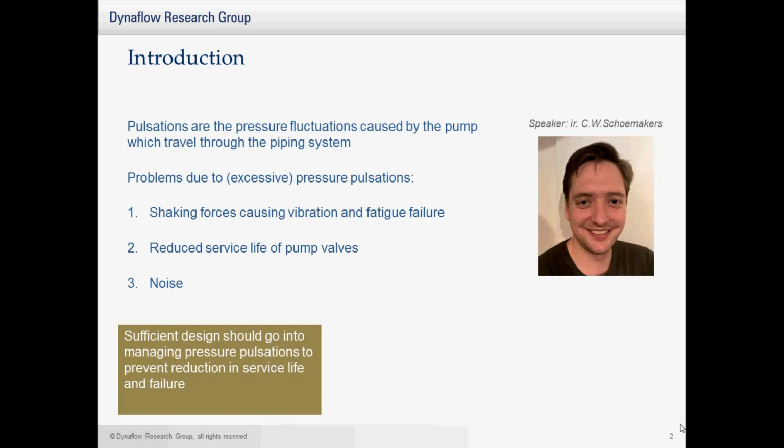So first of all, why is this interesting? The main problems due to excessive pressure pulsations are the shaking forces causing vibrations and fatigue failure. This is really the main issue. And other issues are reduced service life of pump valves and noise. And at the end of this webinar, you'll see that you should definitely pay sufficient attention in the design to managing pressure pulsations to prevent failures.